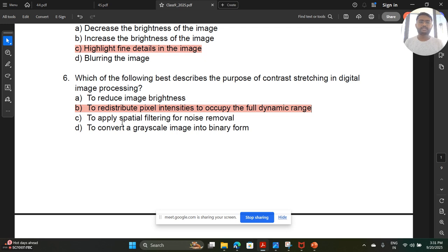You already captured the photo, and anyway you have excessive range available because your object has very little color variation, so you are trying to show more variation. When we design sensors, we design for lots of things, but when capturing we are doing it for one particular object or part of an area, so it will not utilize the full range. That's why we do contrast stretching, to use the full range.